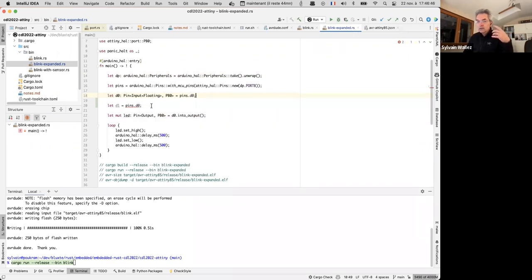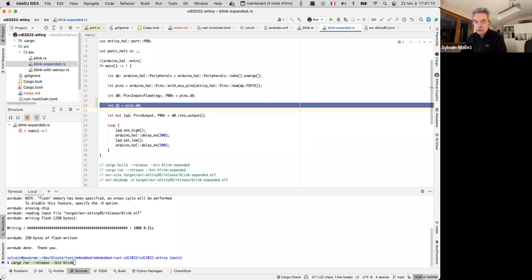So by the simple use of the Rust type system and this singleton, we guarantee that no two functions in your system will try to access peripherals at the same time, which avoids mistakes like one side of the software using it as an input and the other one as an output, and then having hardware conflicts accessing the peripherals.